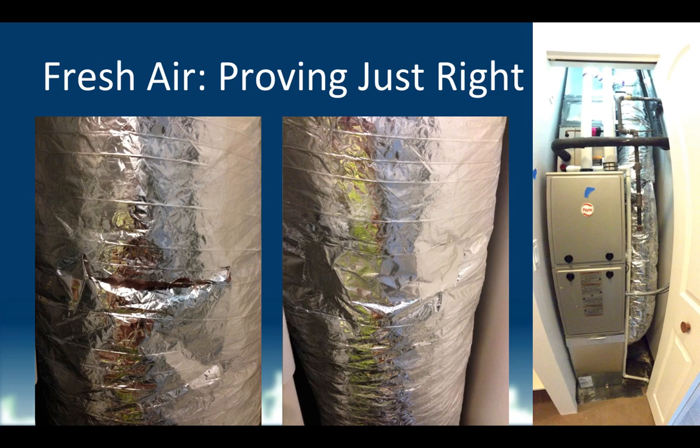By the way, if you want to know if your piece of equipment has been tested, you look for test ports like this. If there are no test ports, there was no testing, period. No matter what anybody says, oh, I installed great equipment. No test ports, they didn't test it. There's no possible way they could possibly know that.